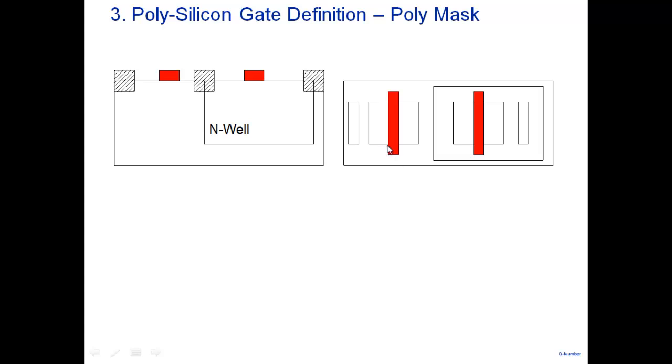So this extra polysilicon, the extra poly that you see here, where is it running? It's running on top of thick silicon dioxide. But the moment it comes into the active region, this polysilicon now is running on top of thin gate oxide. All right, so just keep in mind, this polysilicon versus this polysilicon here. Where is it running? Okay. So I create a polysilicon here and polysilicon here.